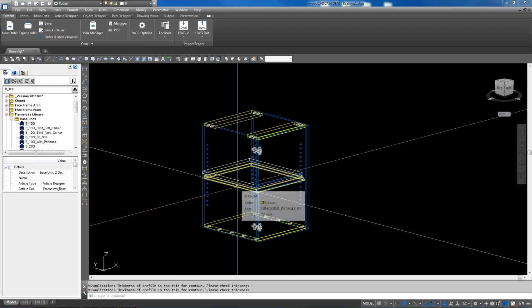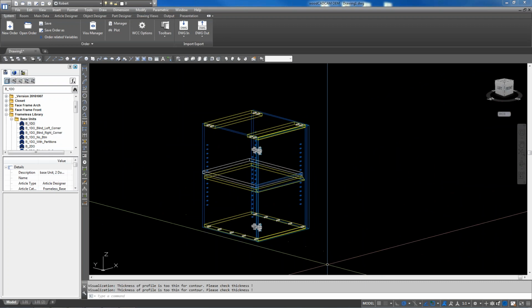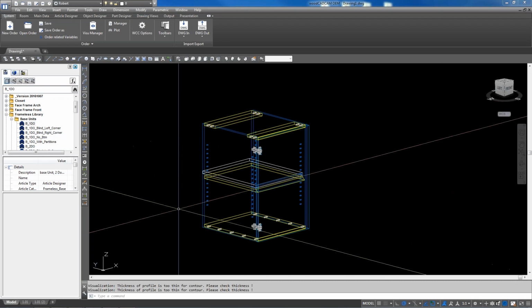So anyway, I would like to replace this cabinet with, let's say, a two-door cabinet, but keep the same size of drawers. So you can replace any cabinet with any other cabinet, but the one that's being replaced takes on the properties of the one you're using to replace it with. So draw me a two-door base in there.